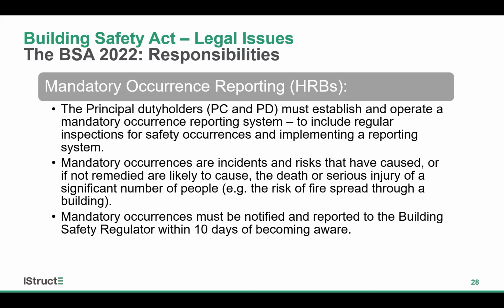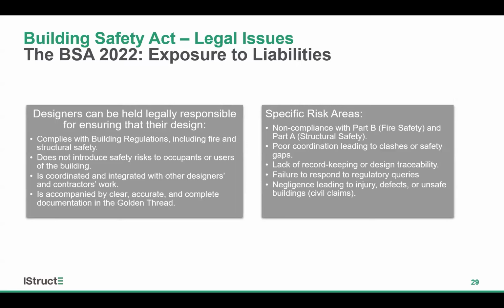So as a structural engineer, where you are the principal designer, it will include establishing and operating a system for doing this and should include scheduled regular reviews and checks of the design. And there's a requirement that any mandatory occurrences must be notified and reported to the building safety regulator within 10 days. So that window of opportunity in and of itself creates an additional risk. So moving on to additional risks then, what additional risks are created by the BSA? Designers are now held responsible, not only to their client under the terms of their appointment, but also under the statute and regulation to the building safety regulator.